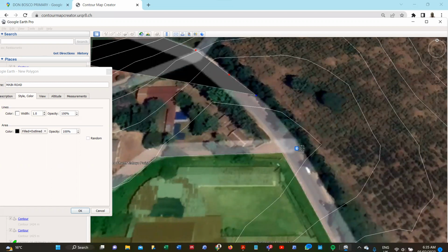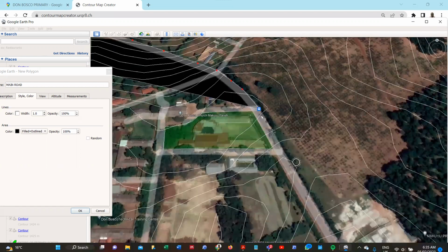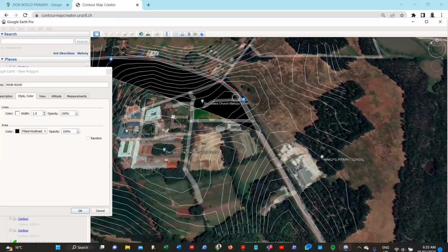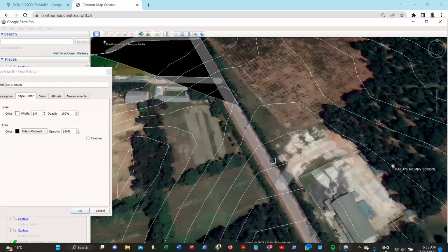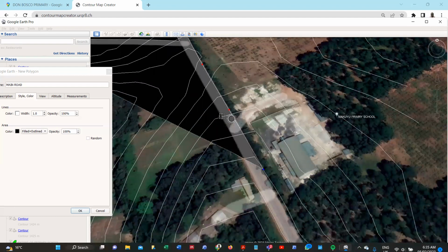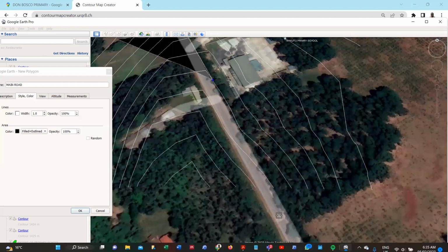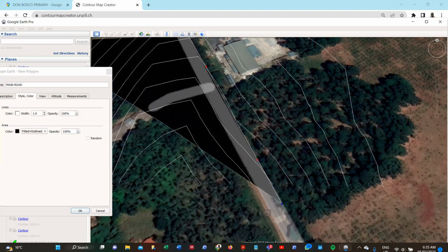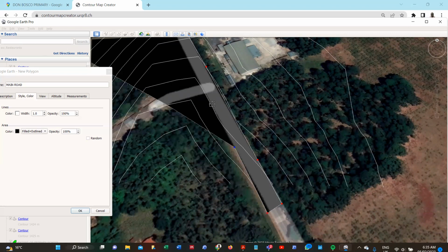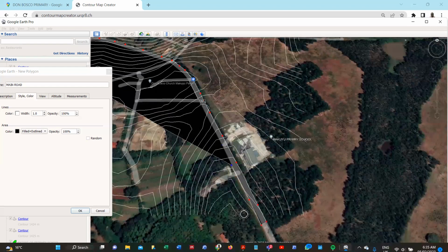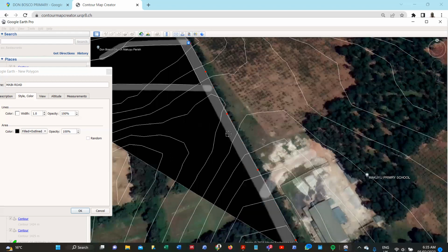When you zoom in, you minimize the possibilities of errors. Remember, I'm doing my road to the extent of our contour. So I'll switch somewhere there and take a corner and start coming back. As you can see, that contrast, you can easily pick up the extent of the road. You lose nothing by zooming in.